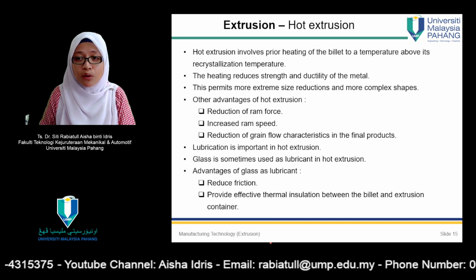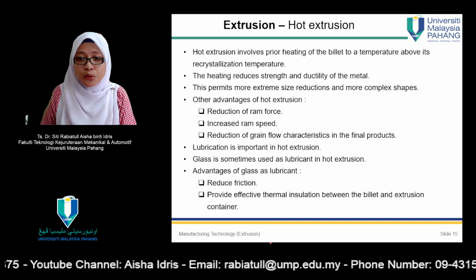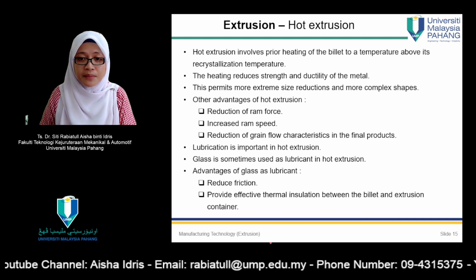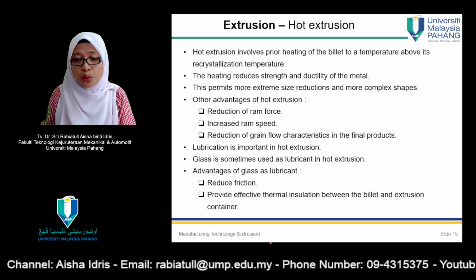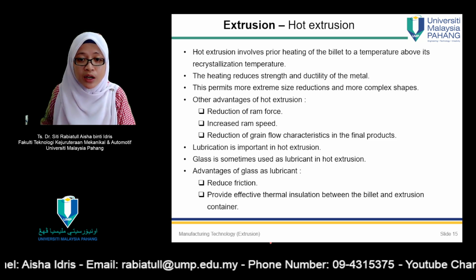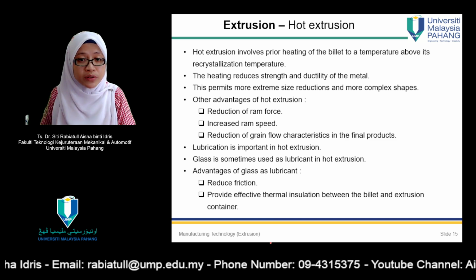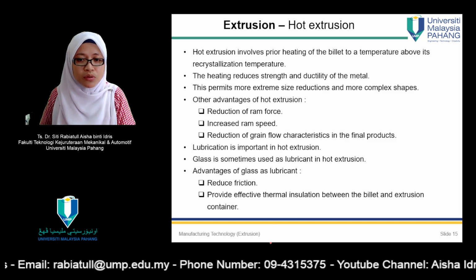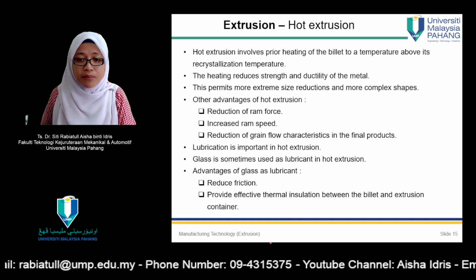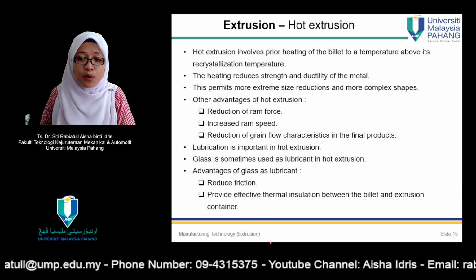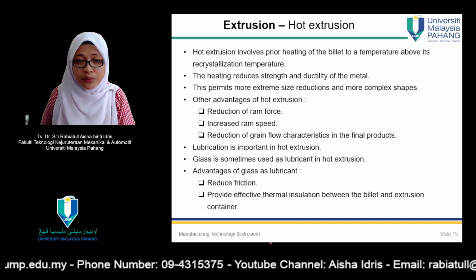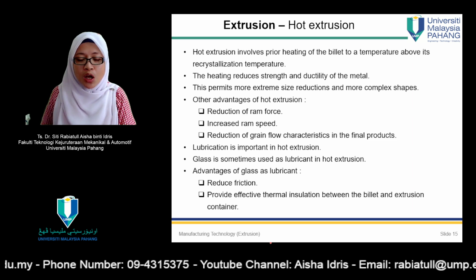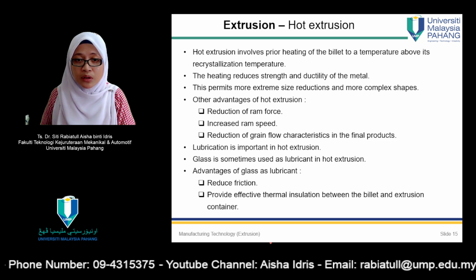So that's why they call it hot extrusion. These types of process also have their own advantages, like it can reduce ram force because the billet becomes much softer. It can increase ram speed, and reduce grain flow characteristics in the final product. So the product will be much stronger.